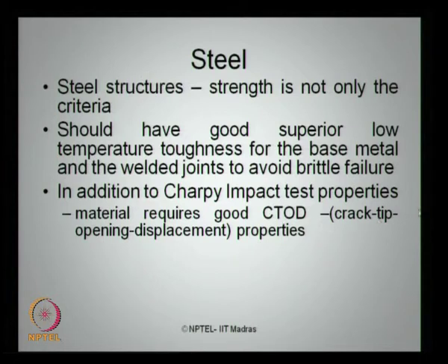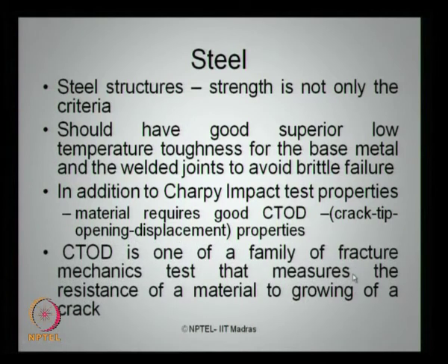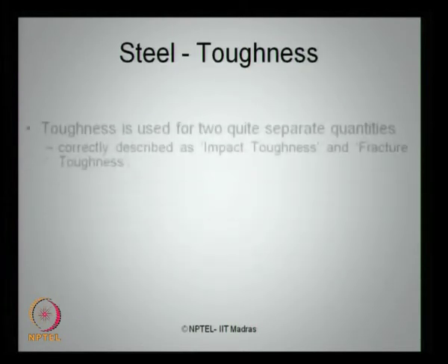CTOD stands for crack tip opening displacement characteristics. They are also important for selecting. CTOD is one of the important family of fracture mechanics tests that measures the resistance of material to growing of a crack. Look at steel toughness.